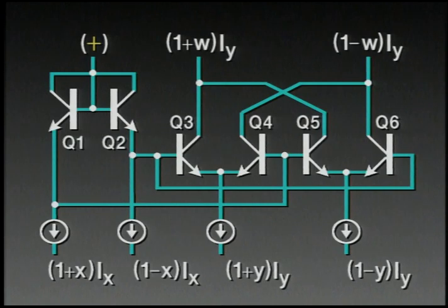This is a very powerful circuit. It's very widely used. Its power arises from the fact that, first, the currents can have any value over a very wide range of values from nanoamps up to many milliamps. The behavior is exactly the same. It's independent of the exact bias currents. Also, as I mentioned earlier, the voltage swings are very small and the circuit can be therefore very fast.